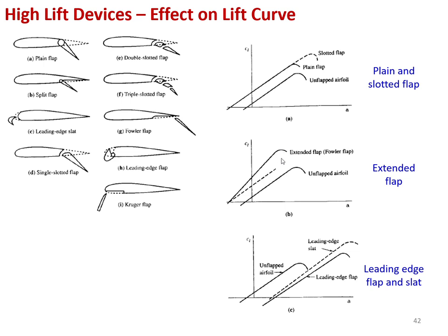So you are going to reach a higher lift coefficient sooner, without changing the zero lift angle of attack location. So your stall angle is going to reduce significantly, but the maximum lift coefficient is going to increase significantly on the other hand. So there's a compromise. You just have to choose here. And the leading edge flap and slats, their effects are given to you in the third graph here.